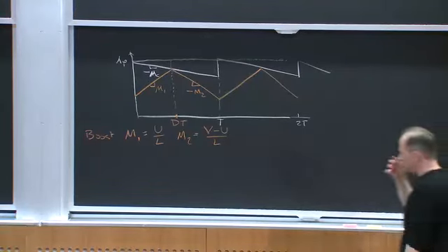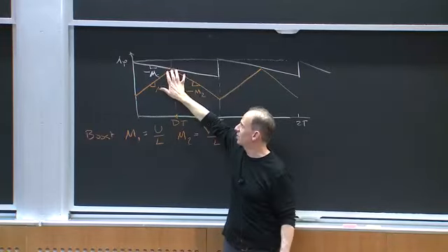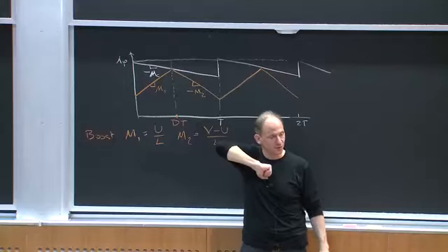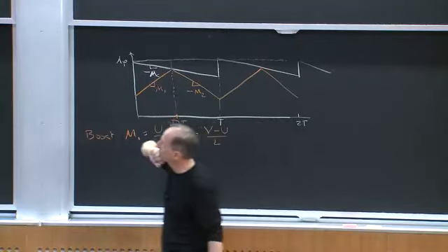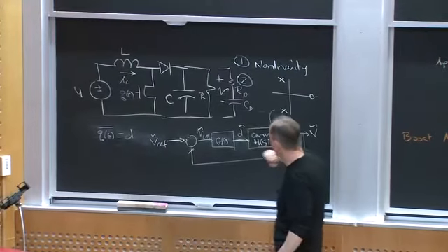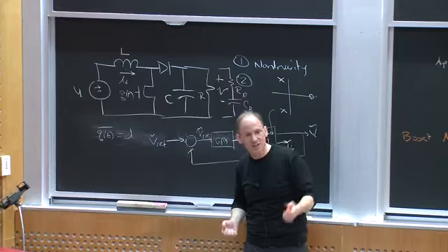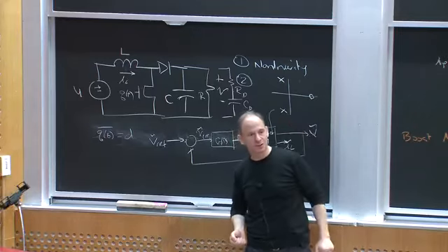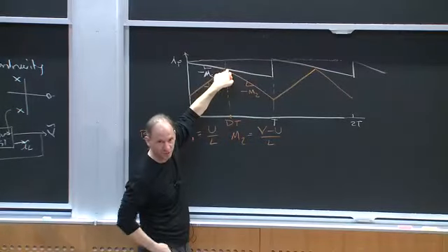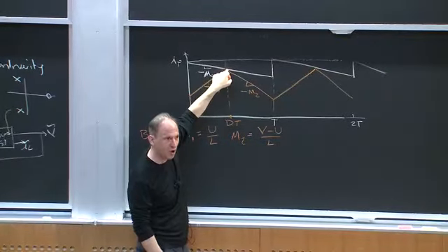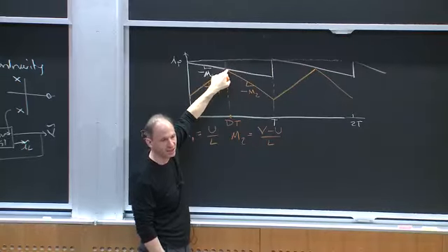So why am I doing this? A couple of reasons. One, it gives us much nicer dynamics, because I'm explicitly controlling the inductor current. The other nice thing is that if I did duty ratio control, what would the inductor current be doing? I don't know. If I put a small resistance on it, it's just going to keep cranking up the current until it does what it wants. Here, I'm telling the switch to turn off if the current gets too big. So this gives me automatic current control. My currents can't get out of control.